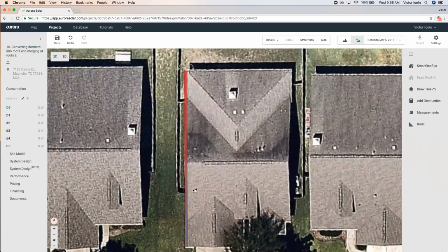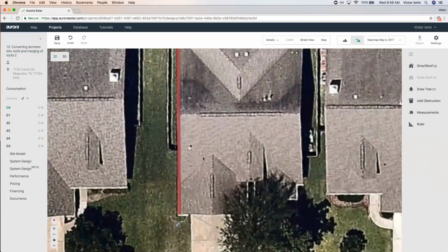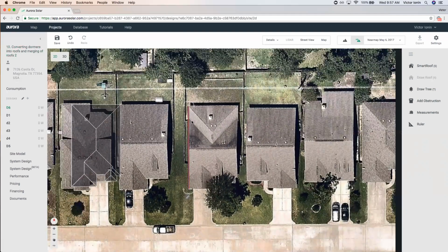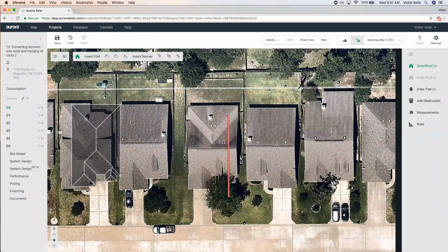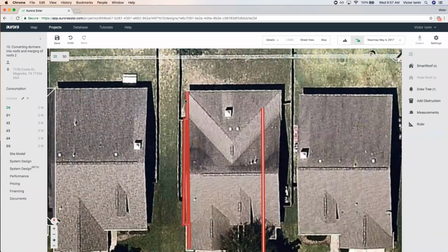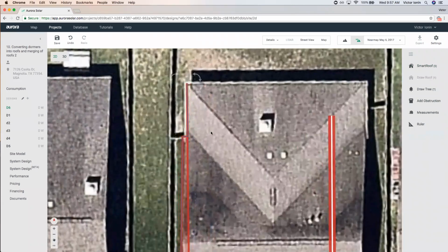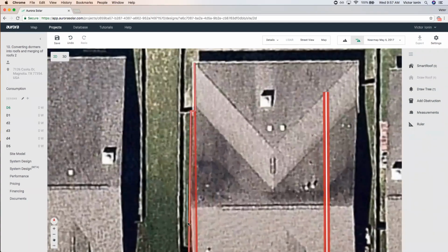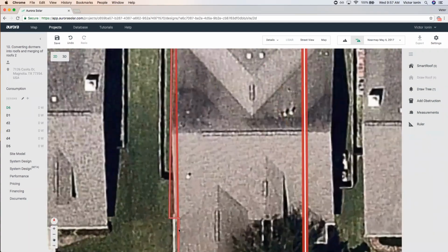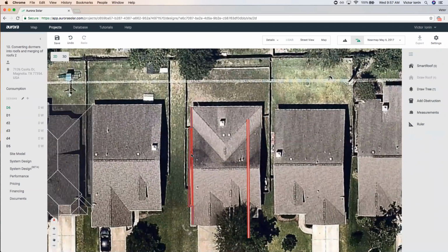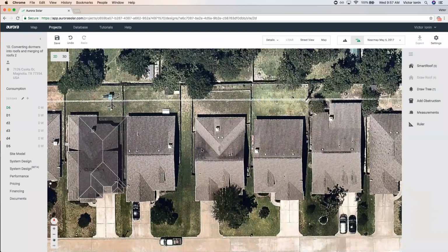Here, it's going to have to be unpitched, so you can have a gabled structure, an A-frame. And then down here, you're asking it to be a west face again, but this time for this dormer. You're asking it to be 3 different things, and that's not going to work well for you. If you wanted to draw this all in one piece, you would need to have drawn three of these lines, so that this piece here can be this west face, this piece in the middle can be unpitched, and then this piece down here can be a west face. So you'd have to do it like that. That gets really complicated. So let's make it a little easier.